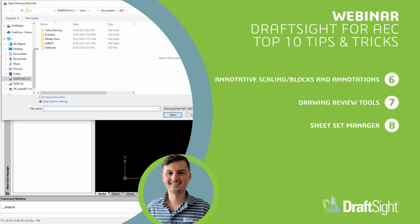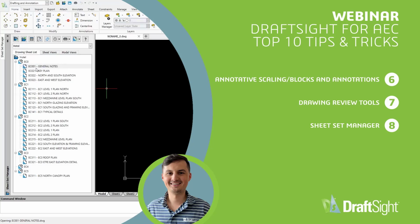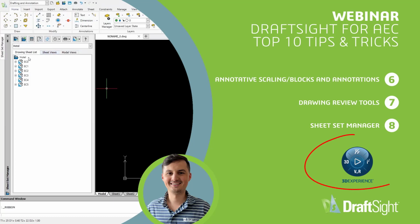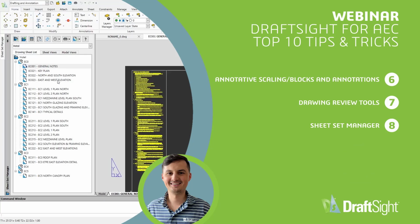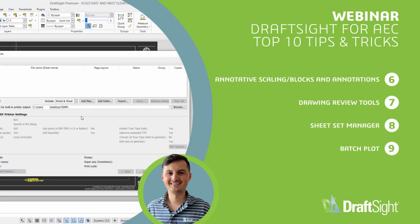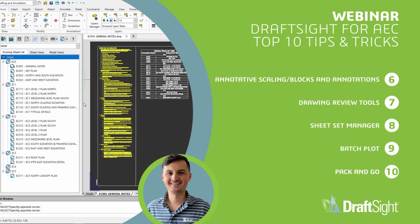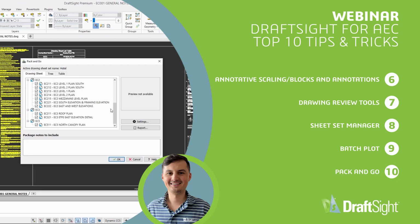And number 8, we are going to talk about the Sheet Set Manager. And a lot of the things that we're going to talk about are actually going to be tied into the Sheet Set Manager. If you see the 3D Experience compass pop up here on a certain topic, just know that we're going to circle back to that specifically when we talk about the Sheet Set Manager. And number 9, batch plot, specifically batch printing to PDFs through the Sheet Set Manager or just through DraftSight itself. And then number 10, pack and go, the ability to share your entire data set with nested XREFs as well as any other file required to open those DWGs.